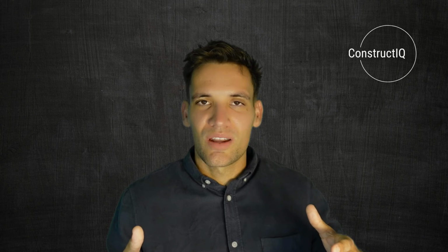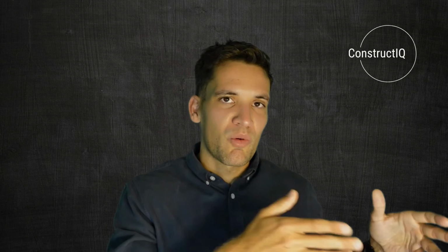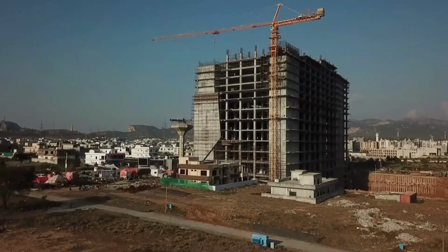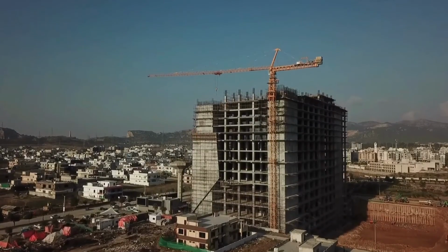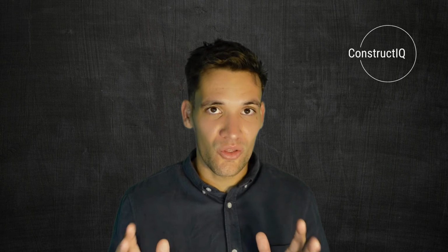So for example, if we're building a building and the project starts, we first need to do the foundations, but to start the foundations, we're waiting on the design. And before we can start the design, we're waiting on the notice to proceed from the client. If the client delaying giving us the notice to proceed is pushing out the duration of the schedule, then that notice to proceed is a critical path activity. If an activity can be delayed without delaying project completion, then it's not a critical path activity. Not all activities are on the critical path, and I think that's the key thing people confuse.